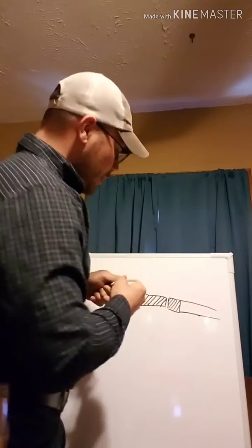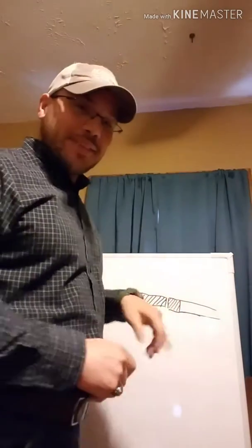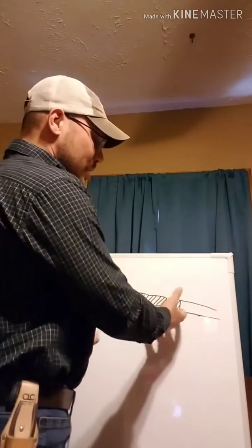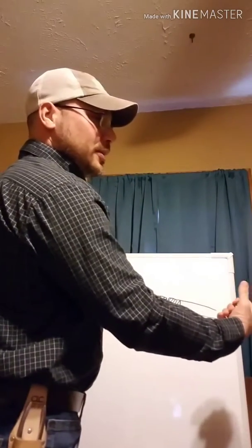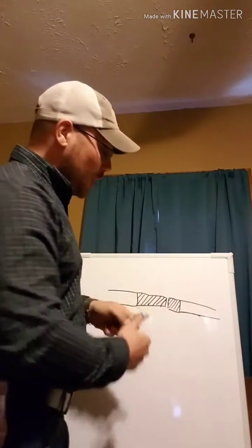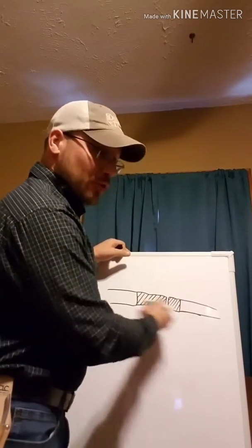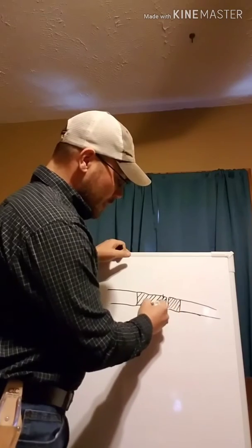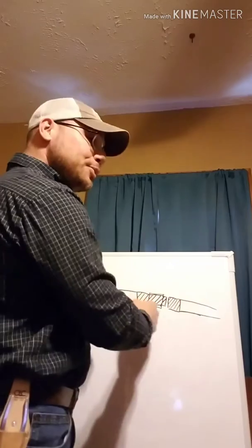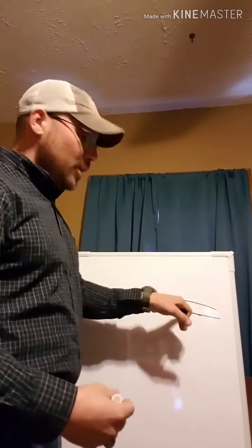If you have, and I'm not an artist, remember that, so those are the same size. If you have a tight location where you can't move these apart and spin them to lock your coupler on, what you can do is take your coupler, if you do those running threads, spin it way back like this, put your pipe up to that, and then you thread it back using a wrench or something and thread it on here this way.